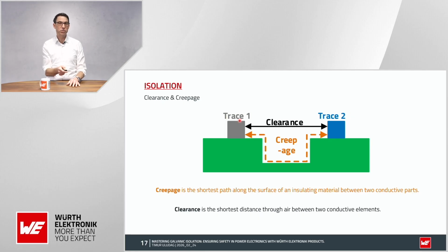The creepage is the shortest path along the surface, that goes here, of an insulating material between two conductive parts. It considers the possibility of surface degradation, contamination, or tracking over time, especially relevant in areas where you have got humidity and dust.